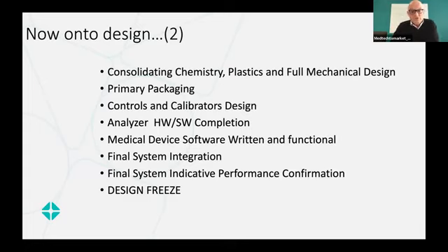And then all the way through to once you've got the hardware and software complete, you've written the software, you've done a final system integration. At that point, you can consider the design frozen. We normally at this point would also do some indicative performance confirmation. So this is where you test it against some of those design inputs. So even though it's a prototype at this stage, the design is frozen, but to satisfy yourself that the design is frozen, you test it against some of those specifications.